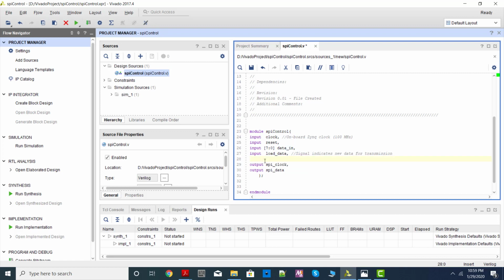Okay, so you need handshaking and a done-send signal or something. This signal indicates data has been sent over the SPI interface. Later we will connect these signals with other parts of the circuit, or to the processor itself inside Zynq, so that the processor can directly send data through the SPI interface with software support. Okay, so basically these are the interfaces.